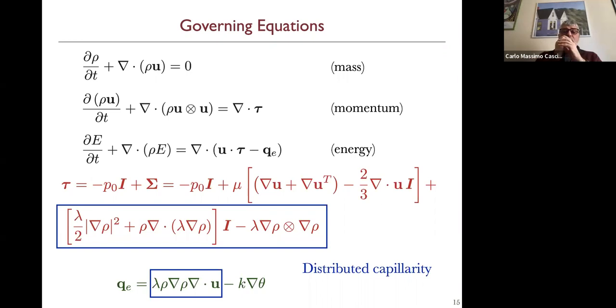If you take an overall look at these equations, you see that they are terribly nonlinear, because on top of the standard nonlinearity of the compressible Navier-Stokes equations, you also have important nonlinearities associated with the density gradients. Nevertheless, once you have built a thermodynamically consistent continuum model for this process, you can discretize these equations, put them on a sufficiently large computer, and see what happens.